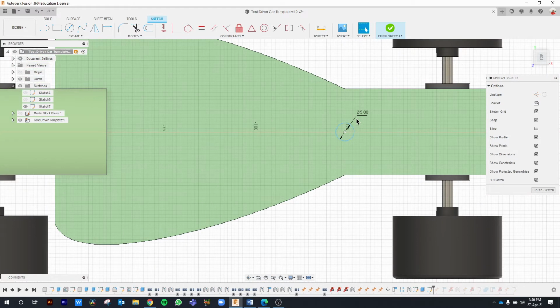That looks good. And now I want to connect this circle to this edge, right? So let's go ahead and create a line first, which goes from the middle all the way to out there. And now I'm going to create a spline that starts from this point. Click at a point in the middle and click on the surface at the edge of the circle that we have previously created and hit enter.